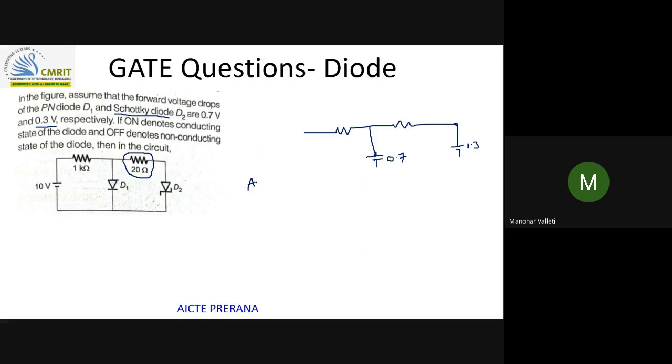So that's why I am assuming. Till now, however you solved the other problems, try to see like that. But here, if some 200 was there, also fine. But it is a 20 ohm resistance. There is ambiguity, more possibility that you won't get the rest of the 0.4 here, so that it will be 0.7, 0.7. It is a very less possibility. That's why I'm assuming, it is just an assumption. D1 is forward biased, but not in conduction, not conducting. To avoid all this, simply saying it is not conducting. D1 is not conducting. D2 is forward biased.